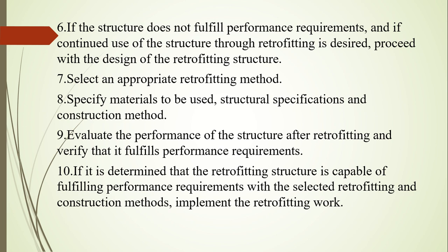Then we have to select an appropriate retrofitting method. The next step is to specify the materials which are to be used, the structural specification and the construction method. Then we have to evaluate the performance of the structure after retrofitting and verify that it fulfills the performance requirements. And if it is determined that the retrofitting structure is capable of fulfilling the performance requirement with the selected retrofitting and construction methods, then we can implement the retrofitting work.